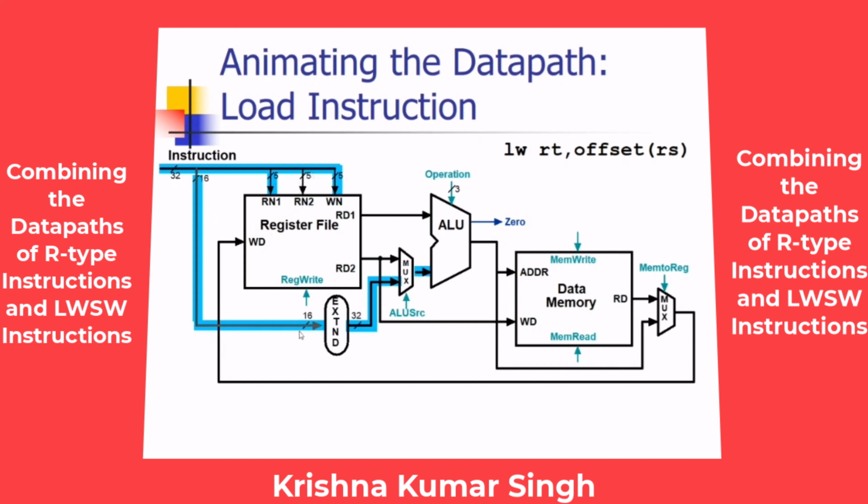Let's check the load instruction. You can see part of the data path is not used here. The 16-bit offset is given to the extend module and converted to 32 bits. And this 32-bit value will be given to the ALU. So again, we have a multiplexer here, and this time the second input of the multiplexer should be selected. So ALUSource should be 1 for the load.